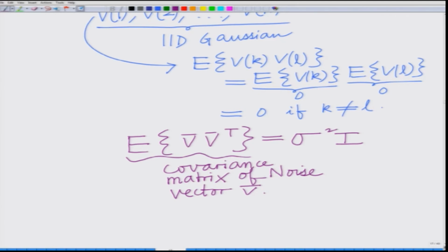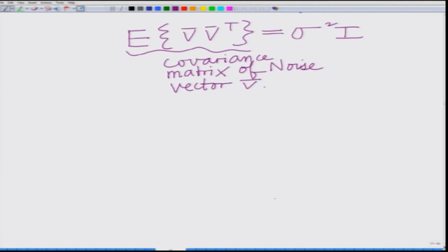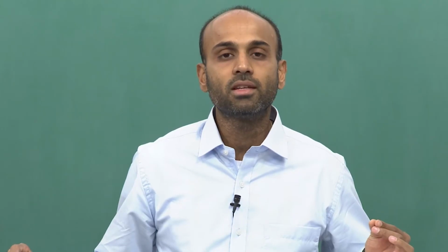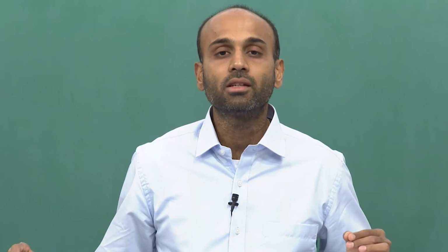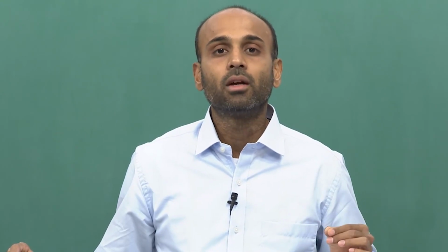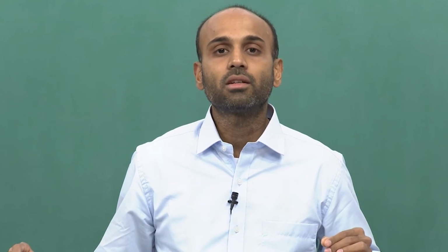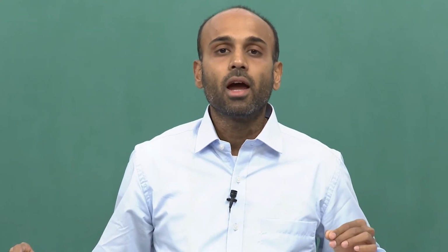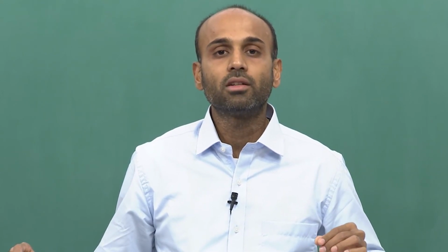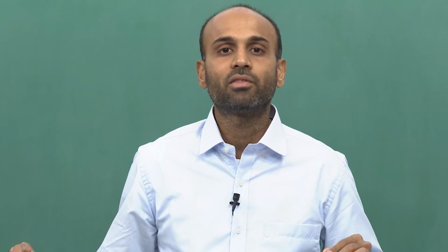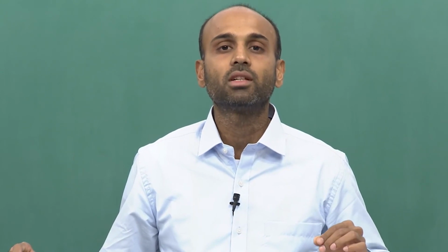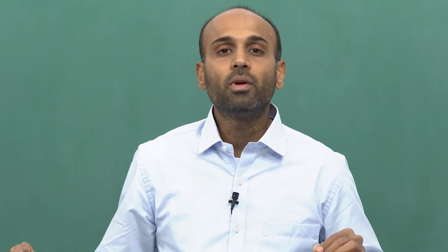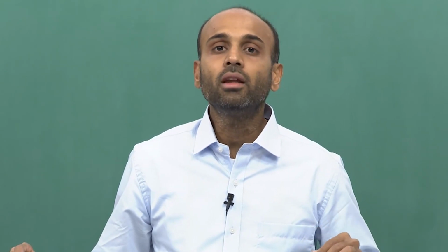Further, similar to the previous MMSE estimation framework, because in the MMSE estimation scenario the parameter h is considered to be random in nature, and since we are considering the Gaussian MMSE estimation framework, we are going to assume the channel coefficient h to be Gaussian in nature.